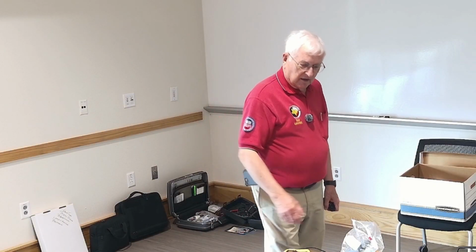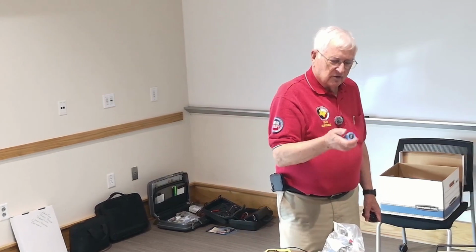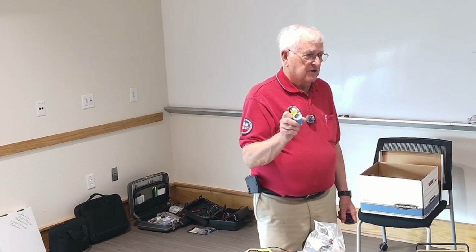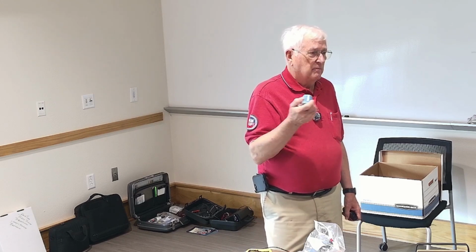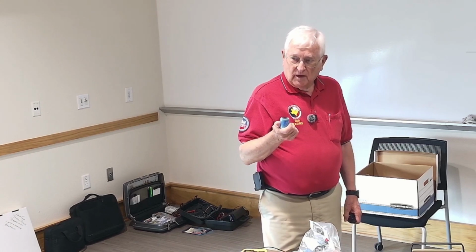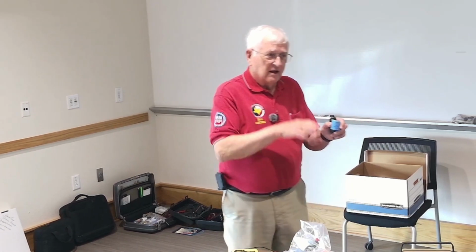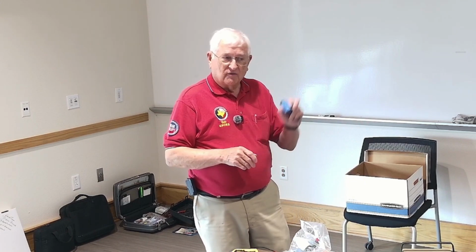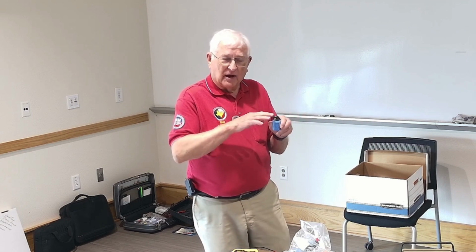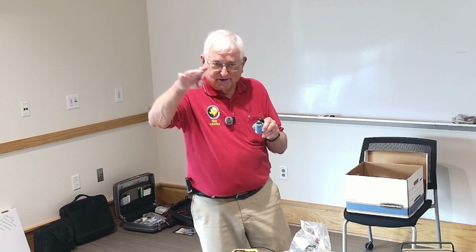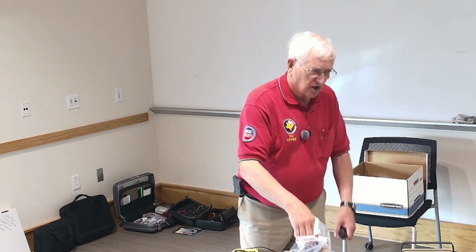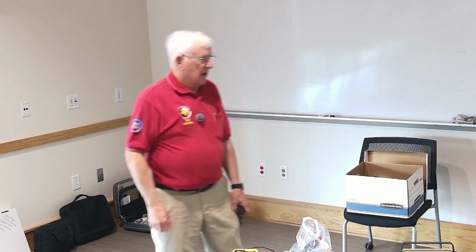Now, some capacitors are made for DC, like this big guy I was showing you just a second ago. This is a 10,000 microfarad at 35 volts DC capacitor. It's a filter capacitor. It's made to be attached to something in DC. The idea being you have the output of a power supply, it comes through this guy, and this stabilizes the output so it remains nice and smooth. If this were not there, the DC coming out of that power supply, if you looked at it on the oscilloscope, may do a little bit of this. You put this on there, it filters or smooths it so that it fills in the gaps and takes care of making the current coming out of a supply nice and smooth.